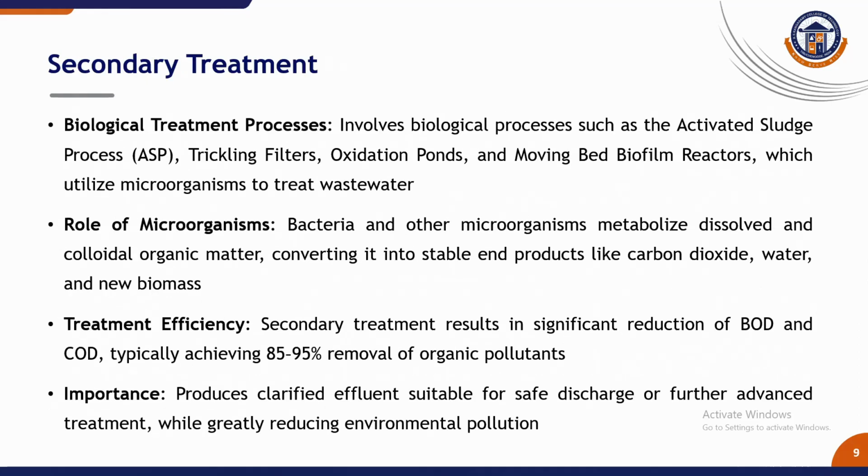Secondary treatment is the most important stage for organic matter removal. It uses biological processes such as the activated sludge process, trickling filter, oxidation ponds, and moving bed biofilm reactors. In these systems, microorganisms consume and decompose organic matter, converting it into carbon dioxide, water, and new biomass. Secondary treatment typically achieves 85 to 95% removal of BOD and COD, producing clarified effluent suitable for discharge or further treatment.